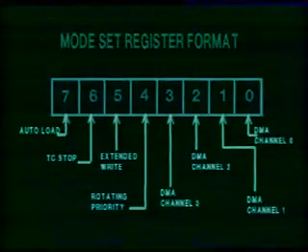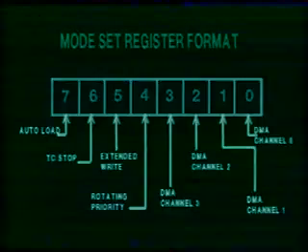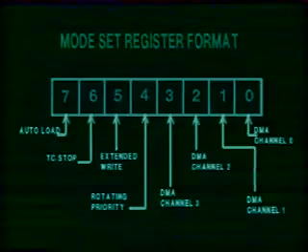Bit D0 enables DMA channel 0. Bit D1 enables DMA channel 1. Bit D2 enables DMA channel 2. Bit D3 enables DMA channel 3.